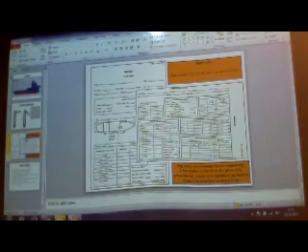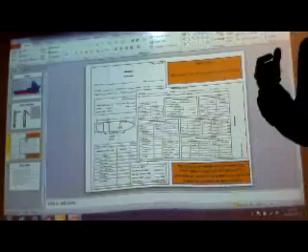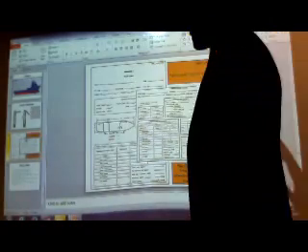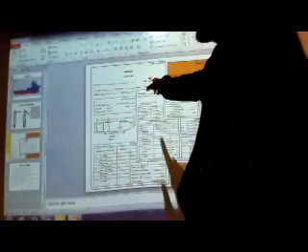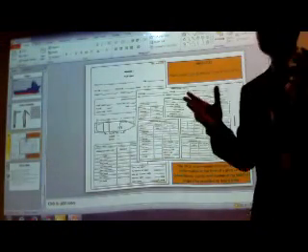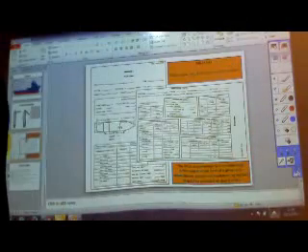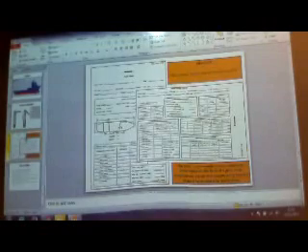Now I'm going to give you a printout after lunch, of the kind of ship that you will be on, which you will have to read yourself, and I will also explain it to you. It gives you all the design characteristics of a ship, including the propulsion system and all the controllable factors, that can be found in your vessel's pilot card. It is one piece of data that can be presented to anybody, and in one very quick view you can find out the design characteristics and the limitations of the controllable factors present on the ship to control the direction and speed of the vessel.